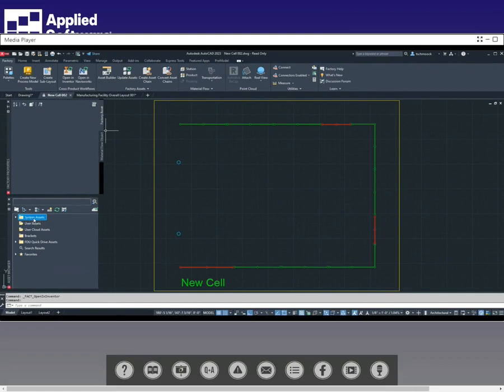This is my asset browser, and I pulled that chain or that fence out of my assets. So as an example, I can search, and I actually used that one right there. And that's how I was able to bring that one in. I just wanted you to see how that would work. What that did is it worked on a polyline, basically. I said, hey, here's a polyline that represents my asset, which is chained, and go ahead and put a fence around that. And then wherever it had to do customized lengths, it turned it red for visualization.